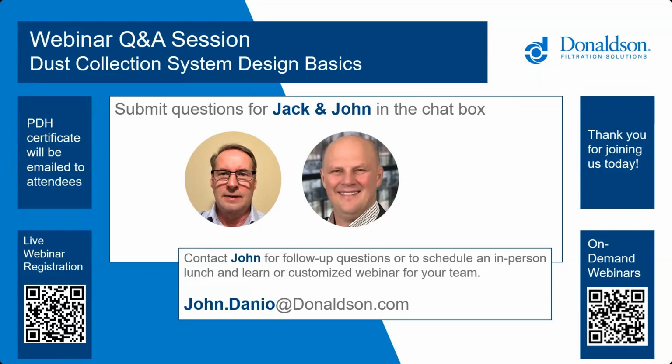On our ductilator, we have grids for velocity, whether it's a vapor, an average industrial dust, or a heavy dust. And I think these come from recommendations from the ACGIH. So there are velocity recommendations per size or type of contaminant. If that person just wants to shoot me an email, I could send them one of our ductilators that has that spelled out. I'm sure it's available in other resources as well. Thank you. Yeah, or we can get you some general information. We can email that to you as well. So it's pretty standard industry guidance on these velocities.